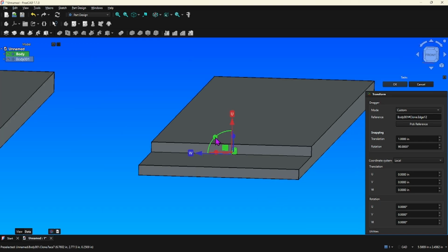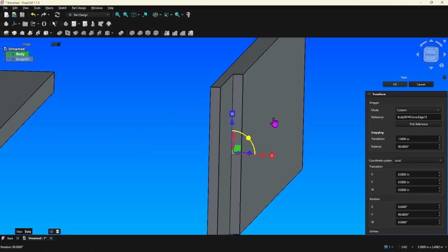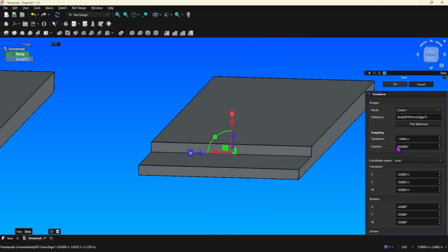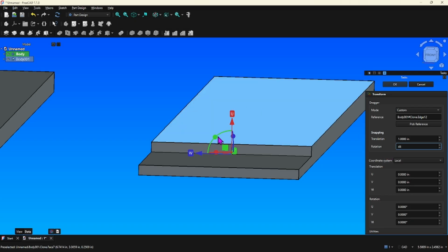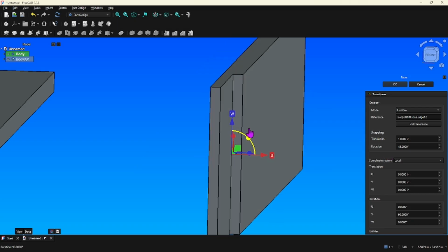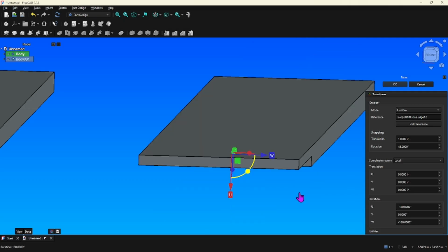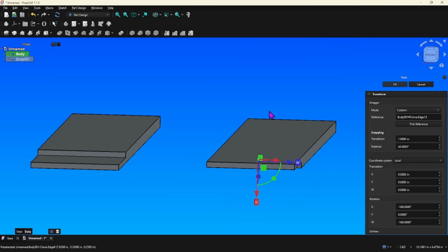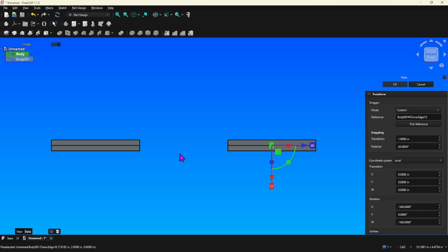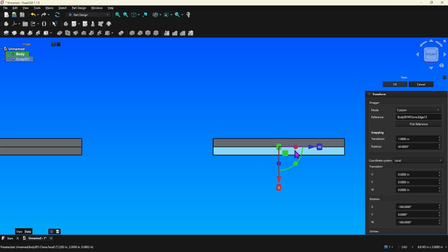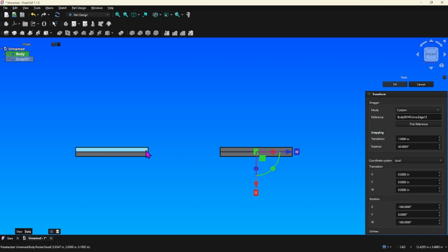And now I can flip this piece over 90 degrees at a time. See how that's set to 90? If I set that to 45, then it'll snap in 45-degree increments. Boom, as I spin it around. Now let me put it on front. And because I chose to use this line here, as I flipped it over, this all stayed on the same plane.